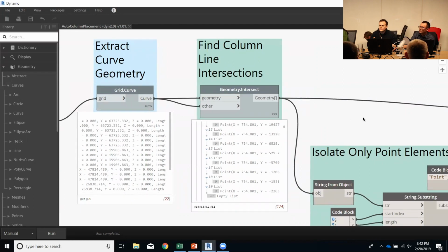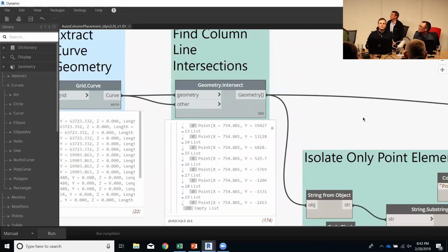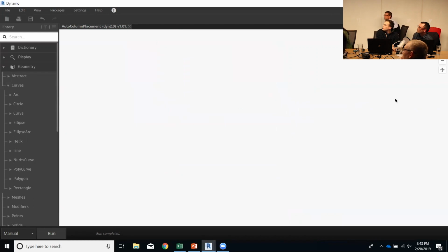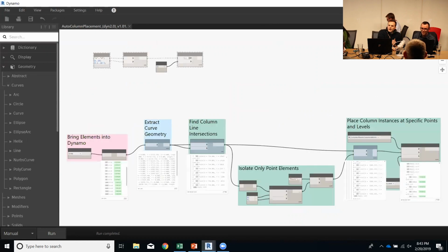And again, this goes back to one of the reasons why it's hard to troubleshoot in a Dynamo environment, is because if I didn't point that out to you, and you were looking at this from 10,000 feet, from the whole overview of the script, you wouldn't have noticed that. So there aren't really good ways to communicate this, and it's just something to pay particular attention to when you're trying to troubleshoot. My first question is almost always, is my list lacing and are my levels set correctly?